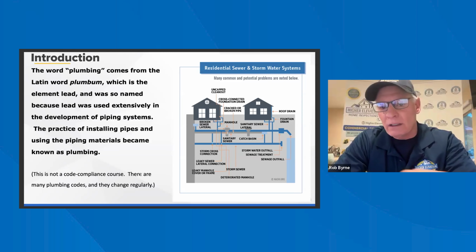Here's our gas shutoff. And again, the drip leg on this one functions both for the furnace and the water heater. We have to have a shutoff on the cold water. We are also required to look for evidence of backdrafting, which would be our exhaust coming into the house. When they have the rubber bushings or gaskets down here, it's very easy to look and see, do we have backdrafting? These both look terrific. So it does not look like we have spillage into the house.